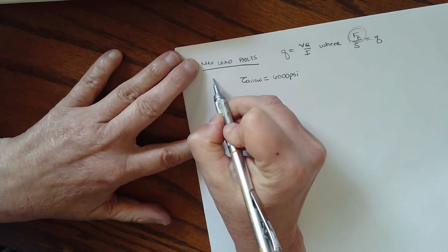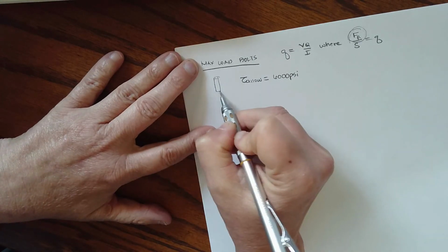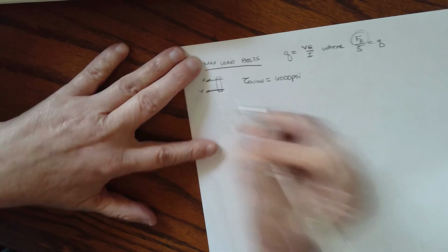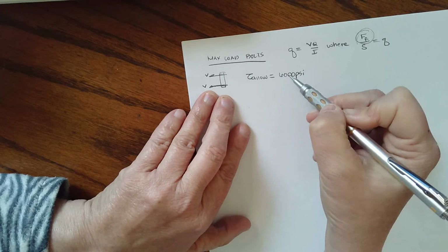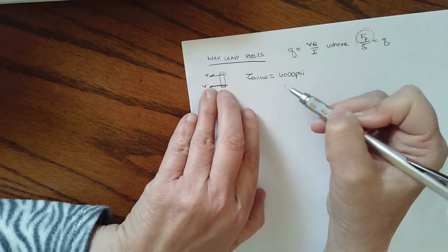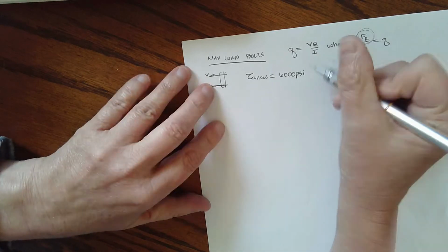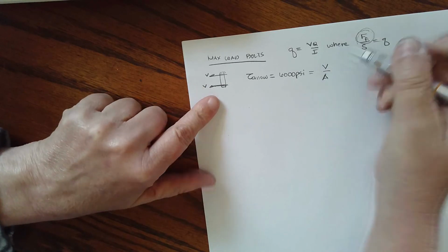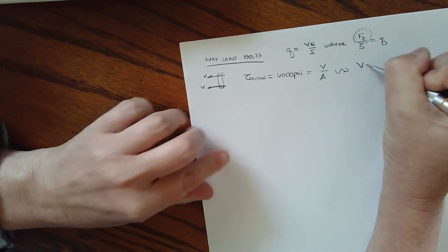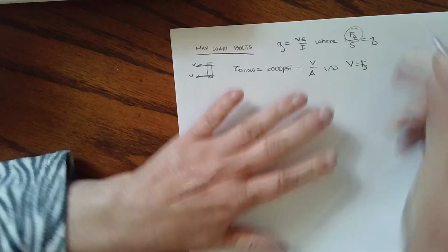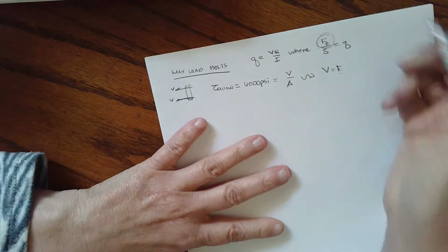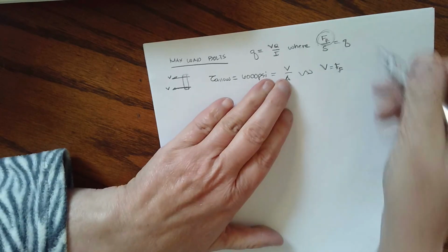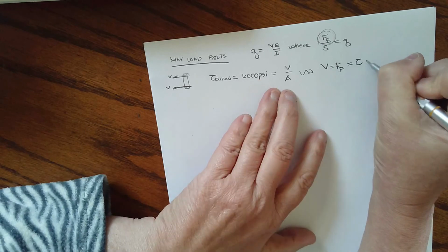And remember, when we have a bolt and it is fastened between something, we are trying to shear. Okay, we're trying to shear, and that's the force we're looking at. What is the strength? If the allowable shear stress is this, how do we find that allowable shear? Well, shear stress equals V over A. Okay, V over A. So V, which is the force of our fastener, equals shear stress times area.